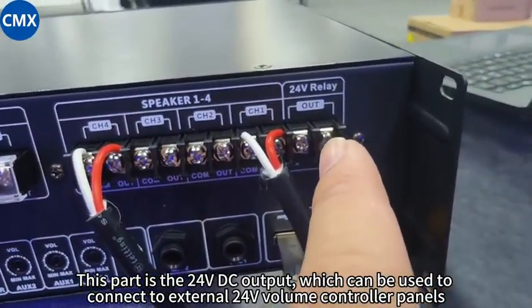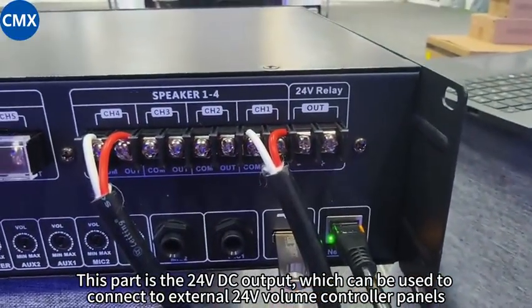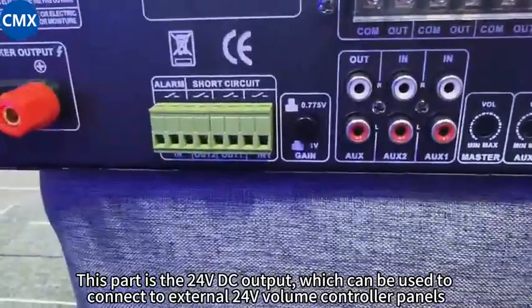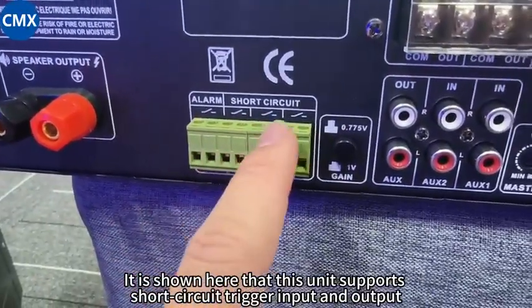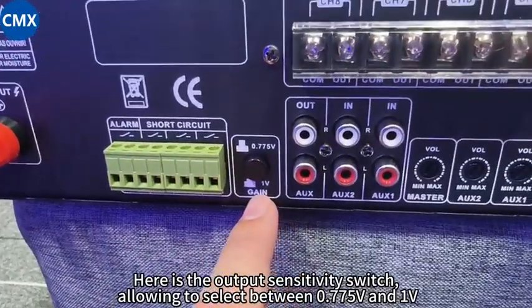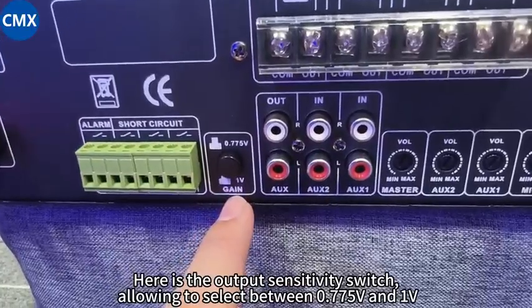This part is the 24 volts DC output, which can be used to connect to external 24 volts volume controller panels. It is shown here that this unit supports short circuit trigger, input, and output. Here is the output sensitivity switch, allowing you to select between 0.775 volts and 1 volt.